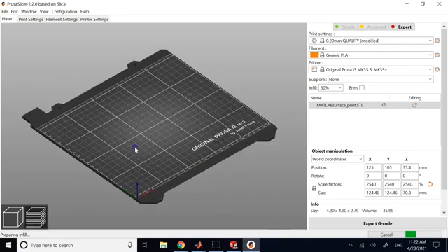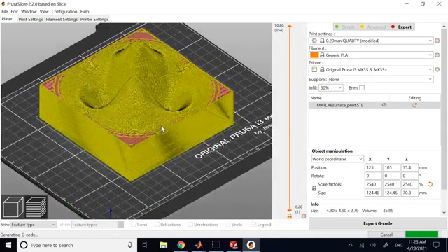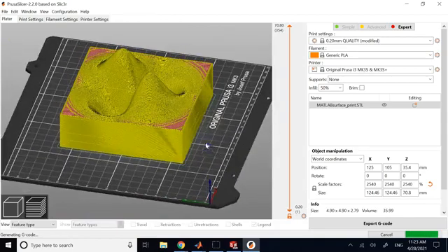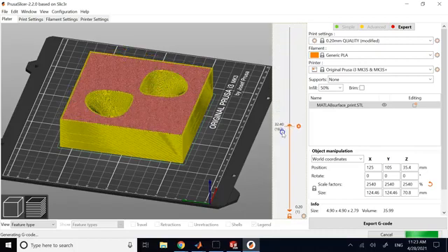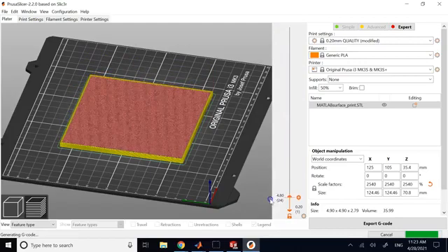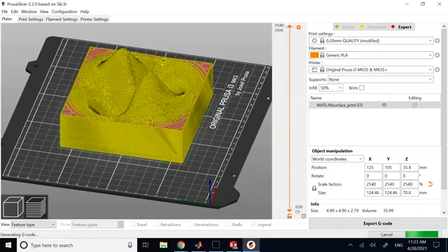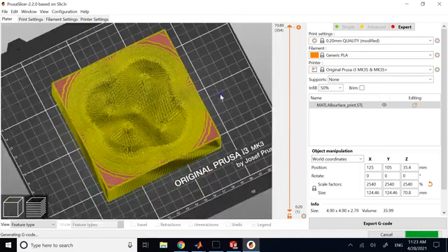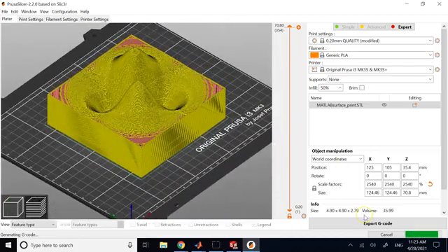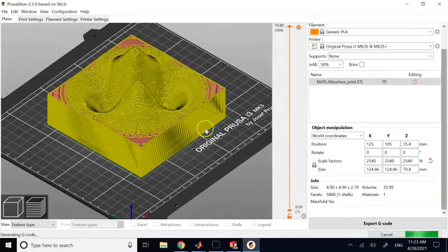Now here it takes a little bit more time in Prusa to slice it because of the top surface, because that's not something simple, but ideally it should be able to slice it, and you see it did. It could slice it for me, and you can clearly see different layers that are generated with so many shells, and it looks just fine. It captures everything that I wanted, and once this slicing is over and the G-code is available, I'm gonna go export it, print it, and done.